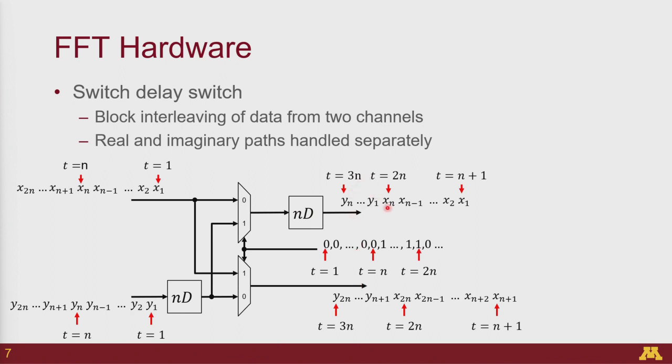One important thing to note when you're doing this kind of system is that in our initial setup this was starting at t equal to 1, but the very first useful values actually come at t equal to n plus 1 here. So this system internally has a latency of n, even though it has 2n delays over here.